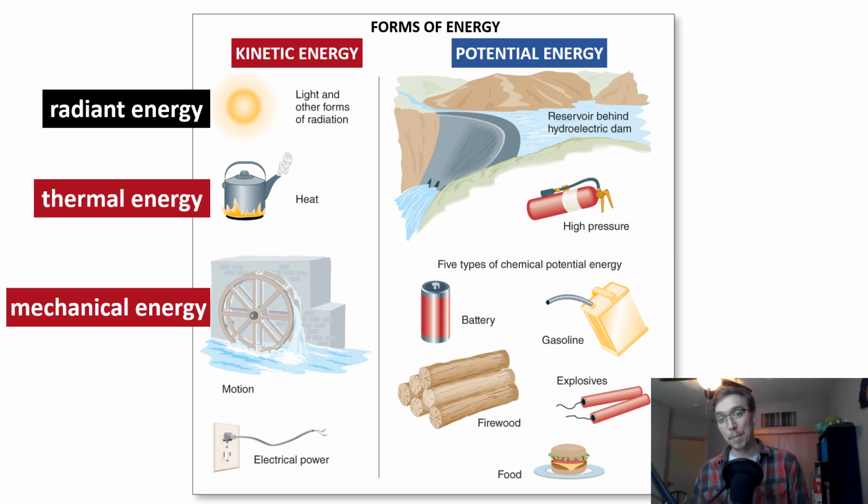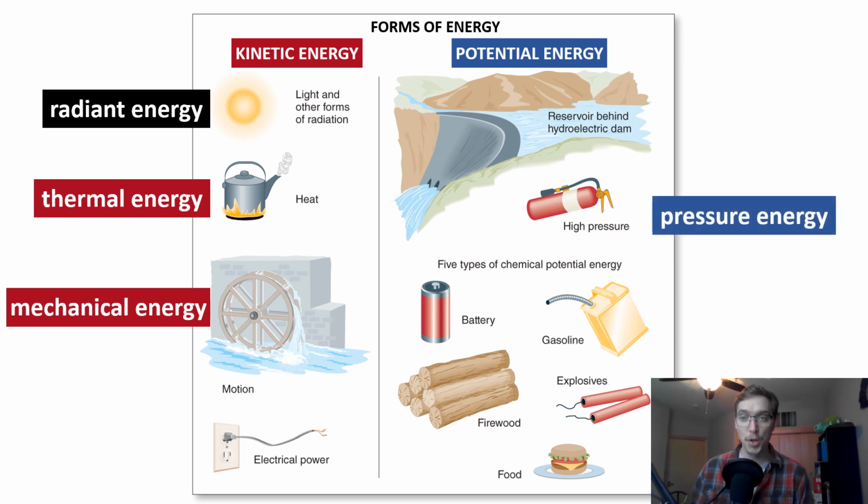Hopping back over to potential energy, the one we're most interested in is pressure energy. Pressure energy is the energy in a fluid due to the applied pressure, as force per area. There is a relationship known as the Bernoulli principle, which drives pressure energy and relates it to potential energy, which we'll talk about on the next slide.